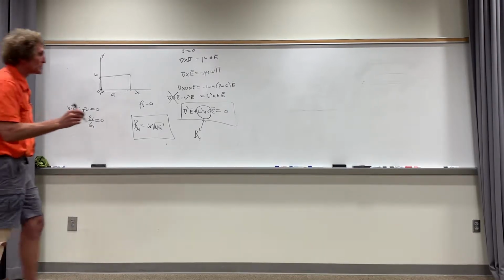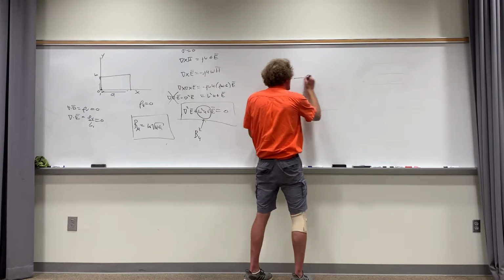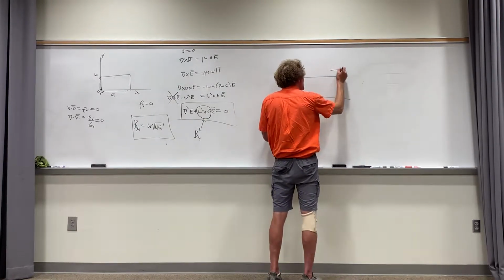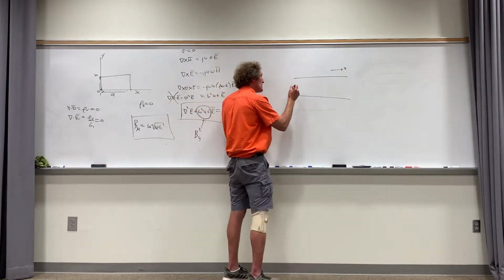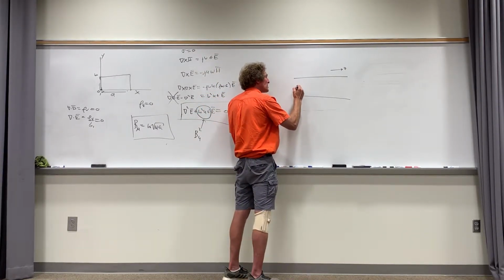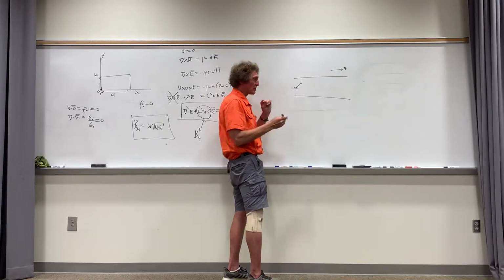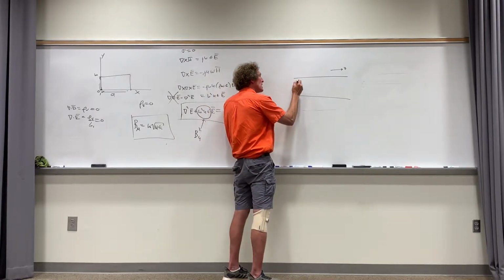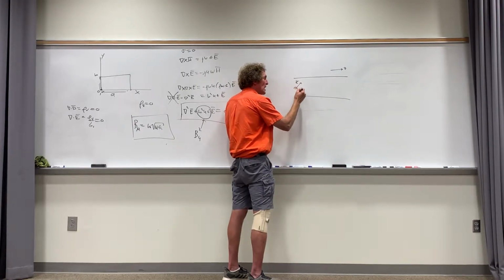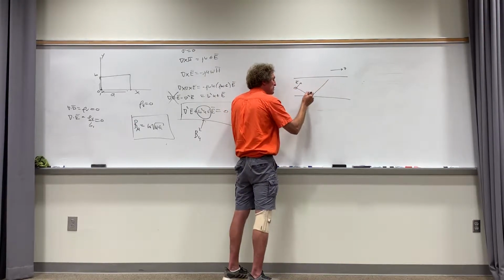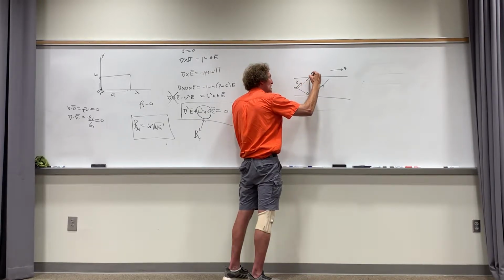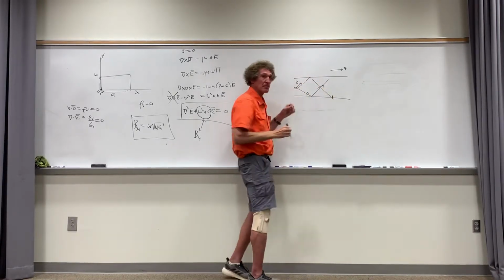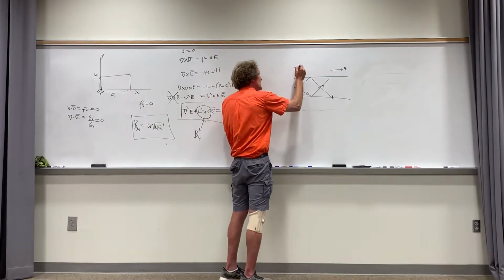Now here's sort of why I'm saying it. Just assume this is the cross section of a guide, and this is the Z direction. Now if you have a wave that's TM, the magnetic field's coming out, but the electric field could be in this direction, and this is something I'm going to show you. The magnetic field's out, that's the electric field. Now you'll notice that the way the waves travel, they bounce here, then here. This is the path. And really you have the superposition of waves. This is one, but at the same time there's also a wave going this way and bouncing this way. Are you with me? Now this is TM mode, transverse magnetic.